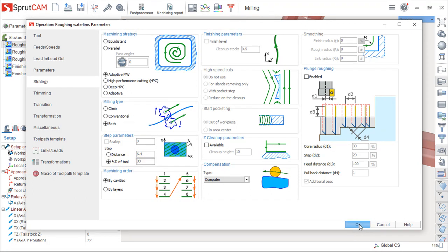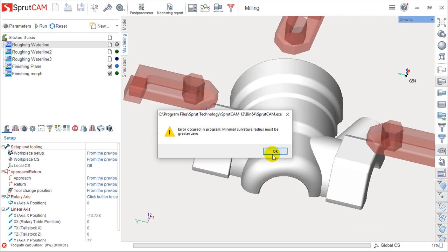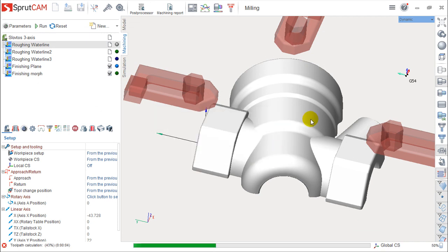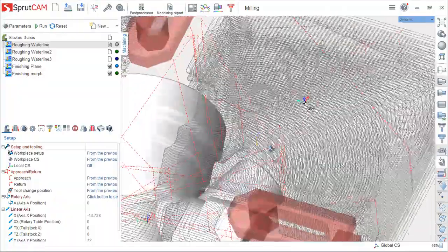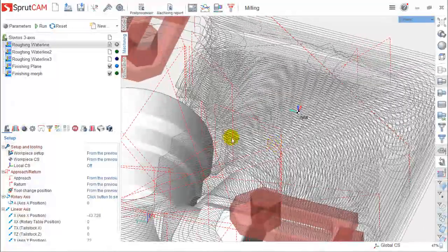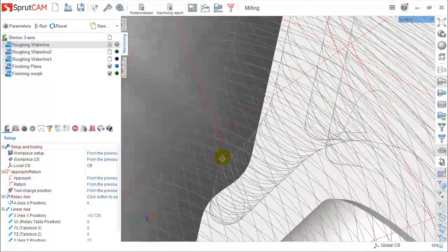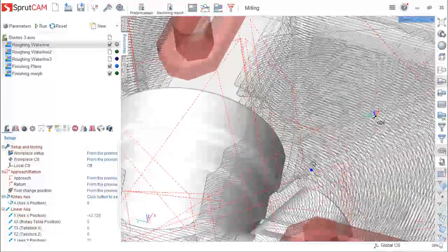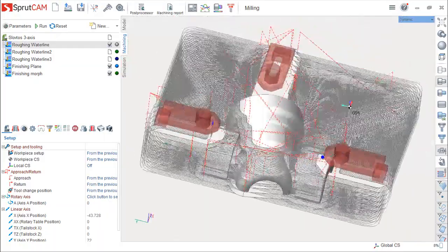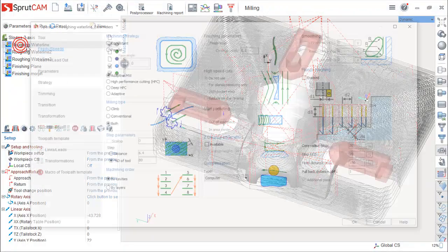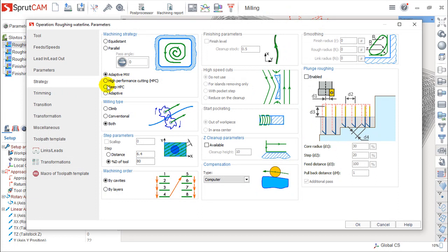which is a percentage of the tool. Okay, I think it will not take too much time. No problem. Let us go and calculate the toolpath. And you see, it is very dense, you cannot see any sharp corner, so it's very smooth for the machine, but you need to have a very fast machine because it will cut a little portion of material each time, but always moving. So very interesting, but you need to have a good machine to have this.